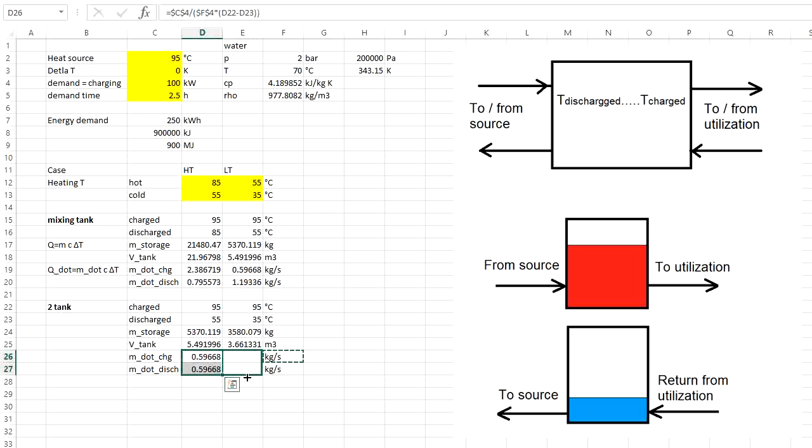And let's see the small tank, where regardless of the state of charge, we also have the same mass flow rate during charging or discharging for the same power, and regardless of state of charge, if it's full or empty, it's just the water level that is changing in the two tanks, and the mass flow rate remains the same, so the operation of all the system is at steady state.